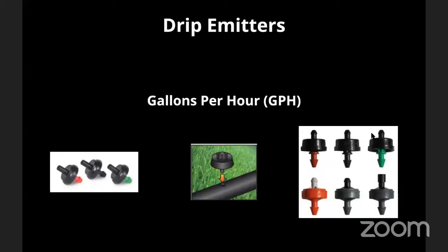So these are the things that are a little bit more common right now for homeowners, and the big box hardware stores sell tons and tons of these, which are the individual emitters that then poke either into the 1/2-inch line. You have a little punch tool that you punch into the line and insert these on it, or they can go to that spaghetti tube. And a system that relies on these, especially when it's newly planted, is to just put 1 or 2 of these at the base of each plant. I would always recommend doing at least 2, 1 on each side, minimally. It's really quick and simple to install.